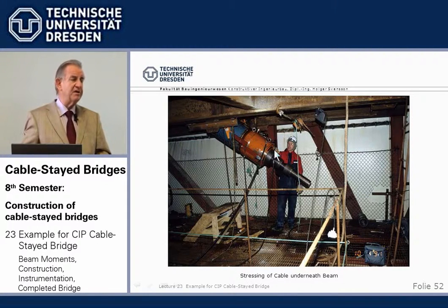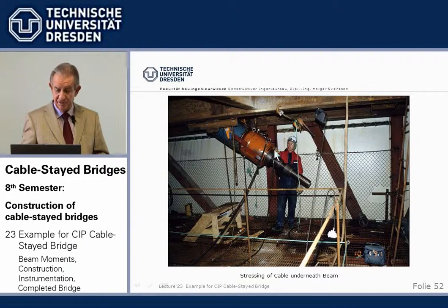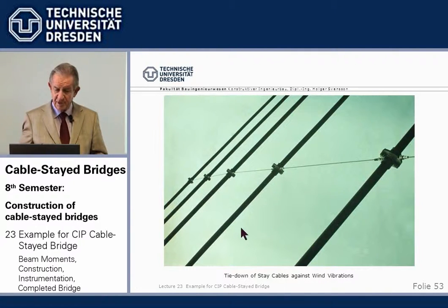Cables showed oscillations, so what we did is we tied them down with tie-down strands, which works quite nicely but has two distinct disadvantages. A, it doesn't look nice. B, it makes it difficult to inspect the cables by a carriage which runs onto the stay cables.